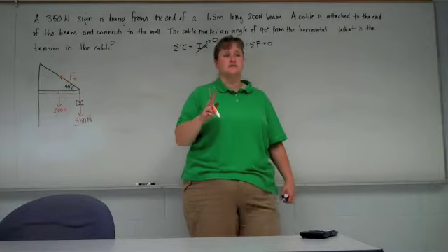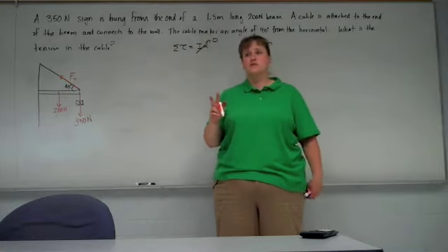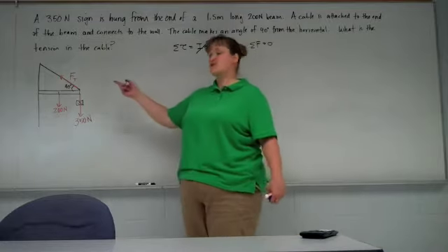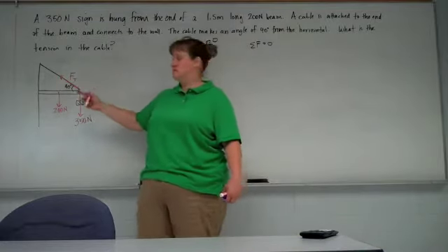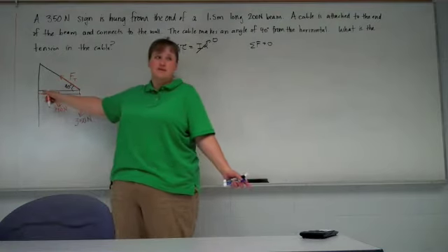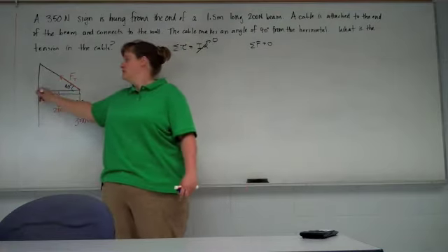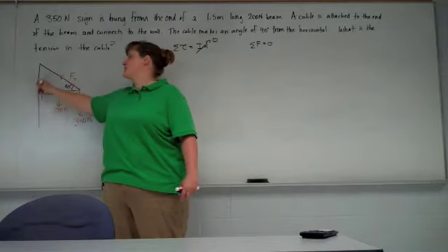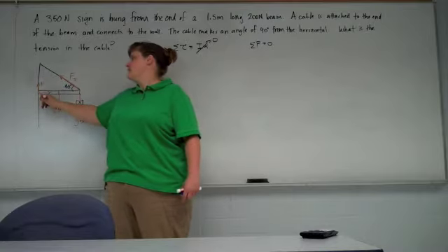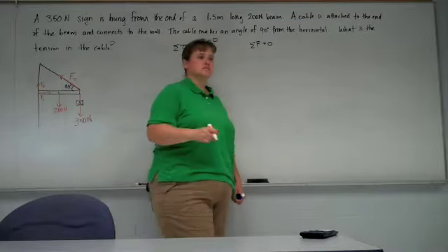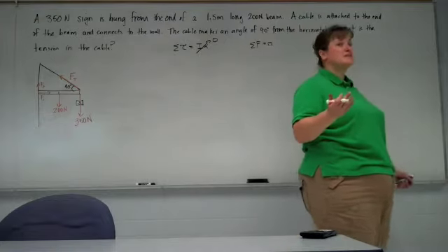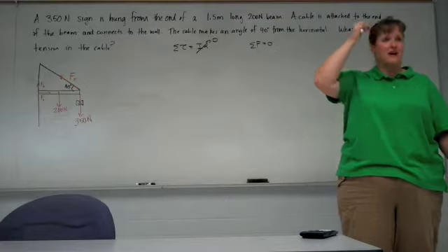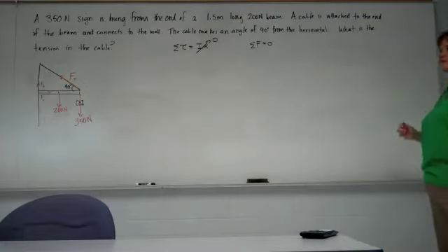Now we have 2 more forces. What forces have we missed? What's the wall doing? The beam's touching the wall, so the wall must be doing something to it, pushing inwards and upwards. I'll call them F1 and F2. If the wall disappeared, the beam would go that way and down. So the wall has to be pushing out and up in order to keep that beam in place.